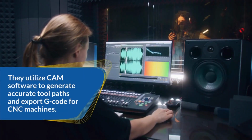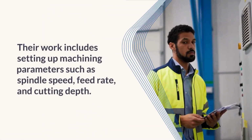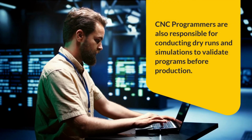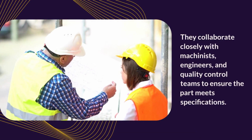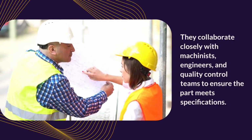They utilize CAM software to generate accurate toolpaths and export G-code for CNC machines. Their work includes setting up machining parameters such as spindle speed, feed rate, and cutting depth. CNC programmers are also responsible for conducting dry runs and simulations to validate programs before production. They collaborate closely with machinists, engineers, and quality control teams to ensure the part meets specifications.